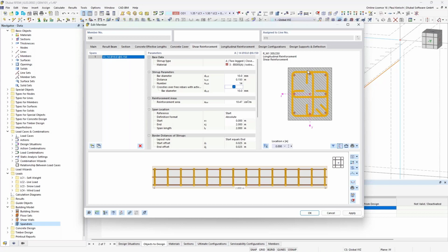And here now, like I said before, if this option was activated, you can graphically activate and deactivate here these shear links. And these stirrups or cross ties will be considered in the shear force design check and also in the detailing design checks.